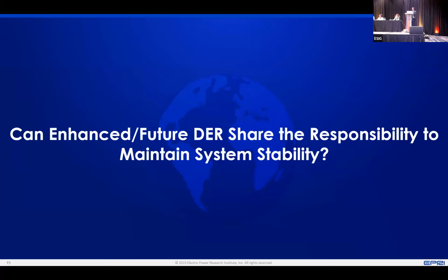So if we then shift the burden, let's see what happens if we have to place something on the distribution network. Keep in mind those two numbers: if there was only static distribution, stabilizing the network on the transmission side was 45 MVA of an additional asset. If there was a dynamic distribution network, stabilizing the distribution network using a transmission asset was 90 MVA, so double.